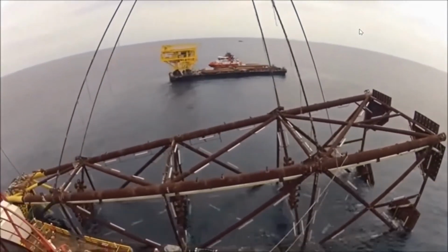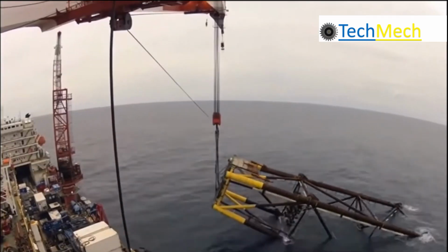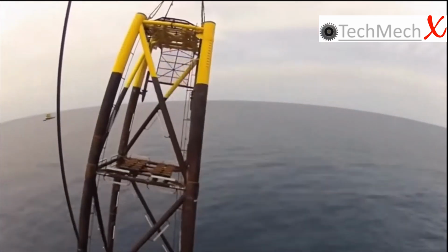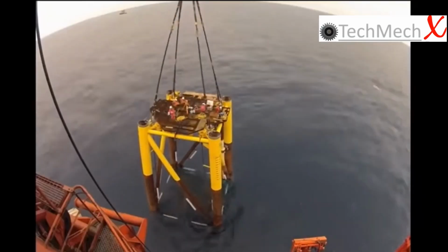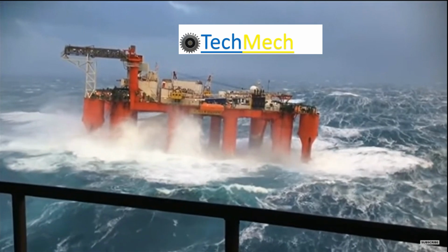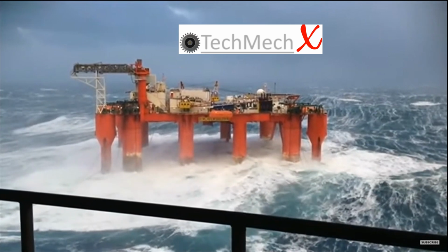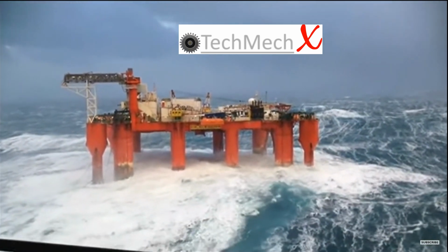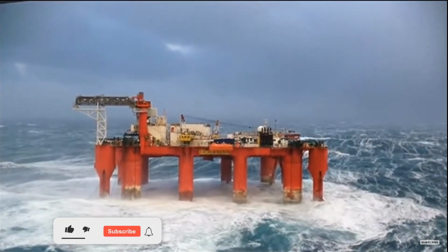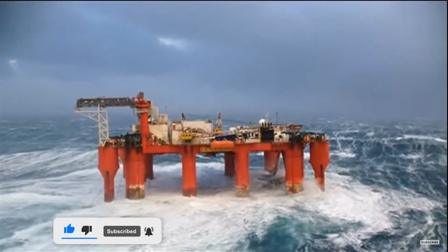In addition to the weight of structures and equipment, these joints are subjected to operational and extreme cyclic loading conditions resulting from normal winds and wave actions or earthquakes, hurricanes, vibration of equipment, and extreme cold, due to which fatigue failure starts and increases as time passes. Loads are therefore either static or cyclic, and the quality of structural welding for tubular connections must endure for the design life of the structure.